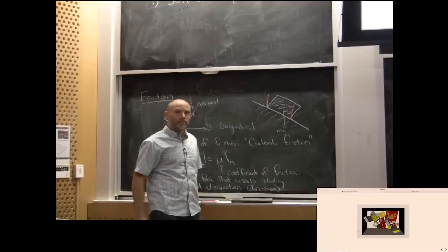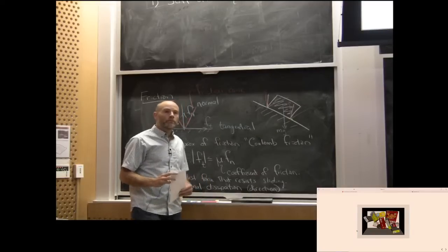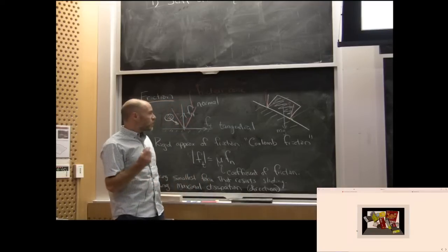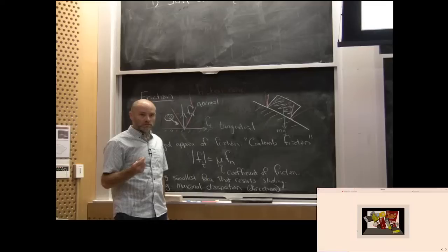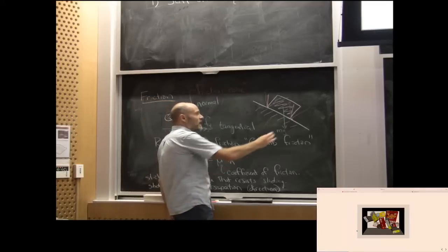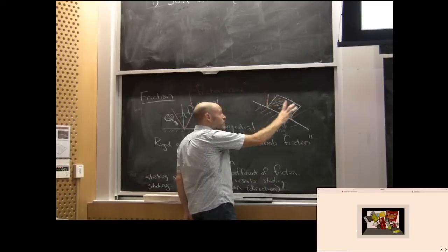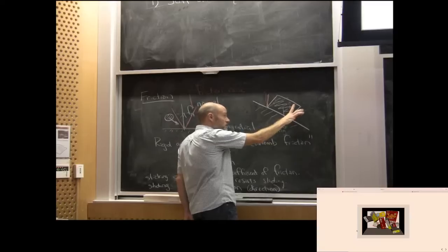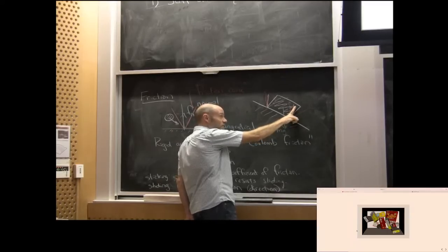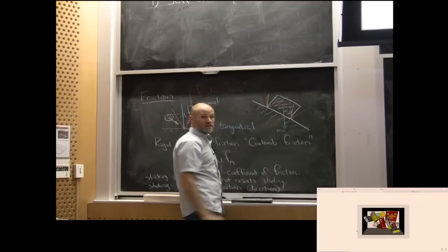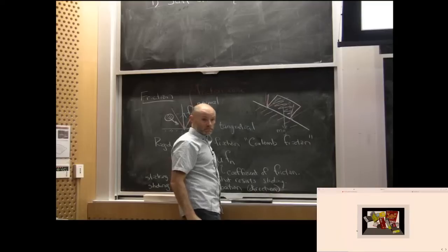Do you want it to be inside the cone or outside? The forces will always be inside the cone. That's the rule. And if I want this brick to stay still, then I would want the friction cone to have a force inside it that could resist that gravity.